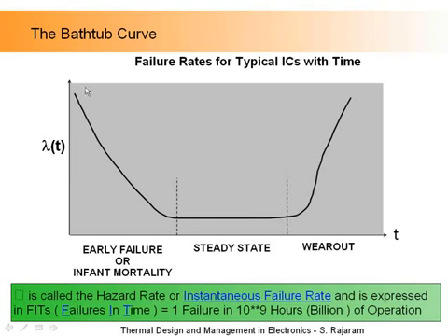This early region is called early failure or infant mortality. And the major cause of failure in this infant mortality is usually manufacturing defects, or component defects from our other vendors. Then once you weed those out, you reach a very, very low failure rate, and the failure here is normally due to design failures. And over an extended period of time, this could be, in the real world, 10 years, 15 years, 20 years.